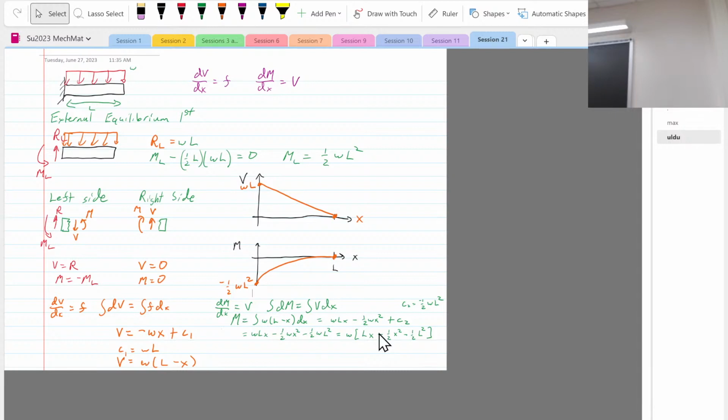So what's the difference between a torque vector and a moment vector? Just a way to remember: they are both kind of the same thing, but J is pi over 2 and I is pi over 4. Torque is applying a twisting, which we associate with the shear stress, and a moment is applying a bending moment, which we associate with the normal stress.